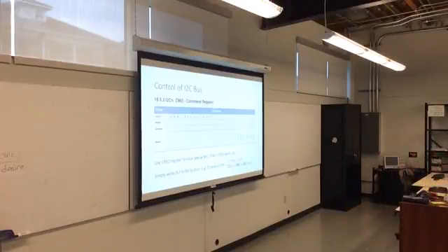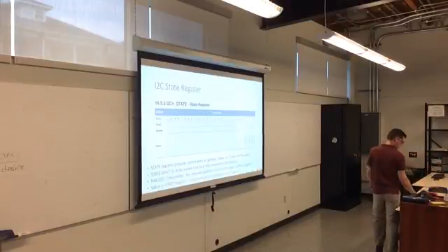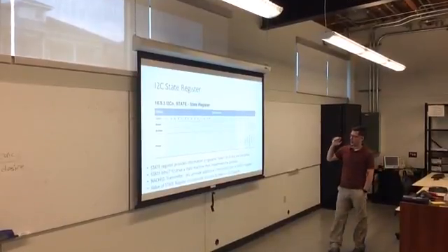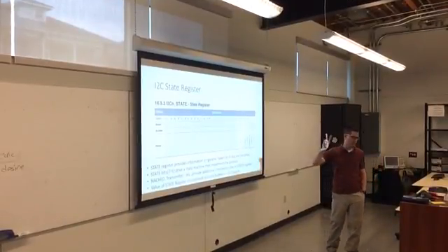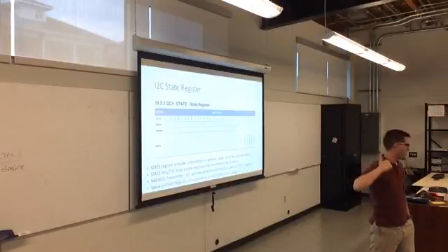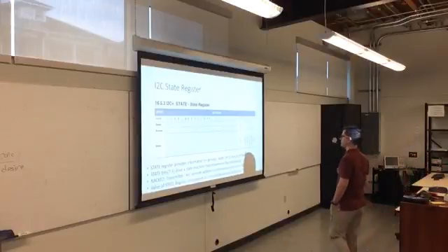At the same time, there are two major registers that tell you what's going on. The state register gives you the general state of the I2C bus. It tells you what's going on. And those state bits, when you're looking on that chart and it says state is 97, it's talking about all of these bits.